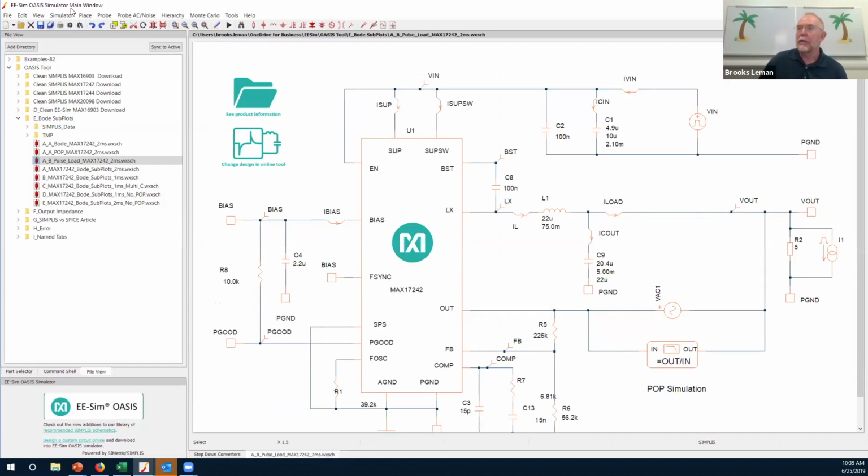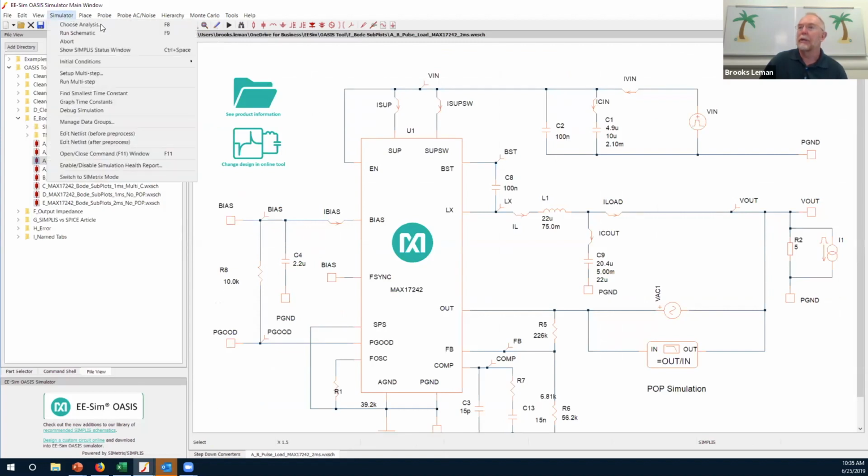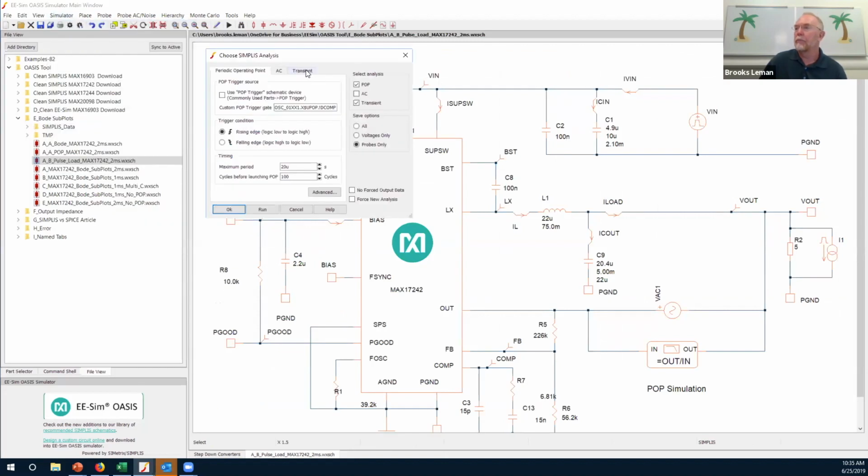We also have to set up the transient time domain simulation. And this is pretty easy. You simply set the stop time. You can actually blank the first part by setting a time here. For example, if I were to put a millisecond here, then I would not take data for the first millisecond.